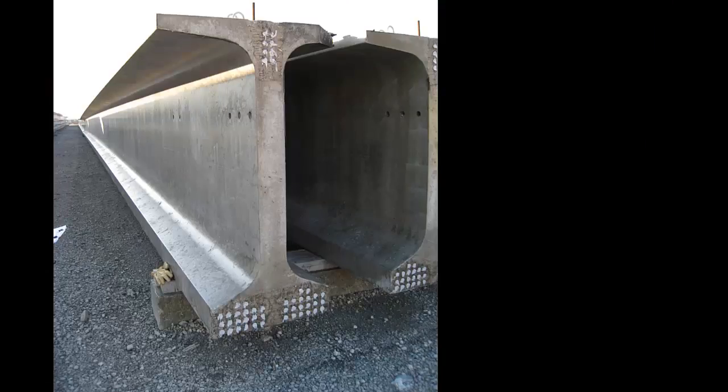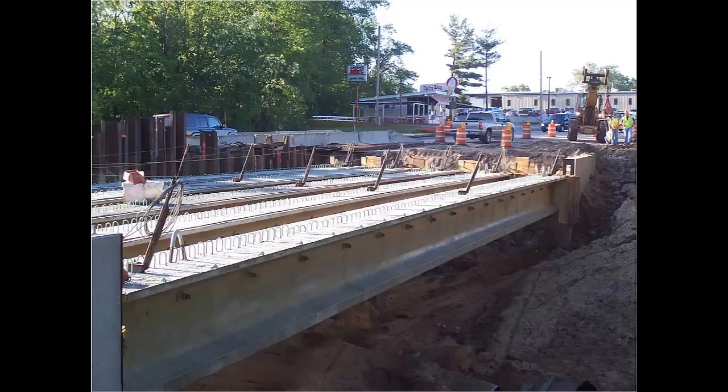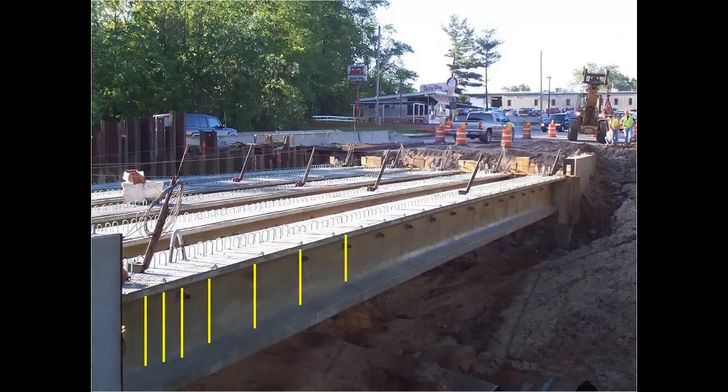In this bridge girder, the size of the bending moments defines the number of steel pre-stressing strands that need to run along the girder length. The shear forces define how many steel stirrup bars will be embedded in the webs. At the girder end, where the shear diagram has high values, the stirrups will be close together. Near the middle, where shear is low, the web may not need any stirrups.